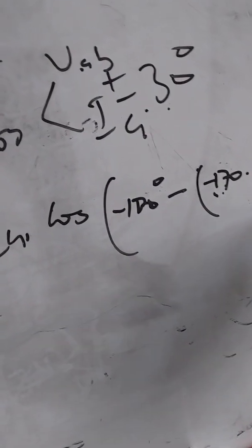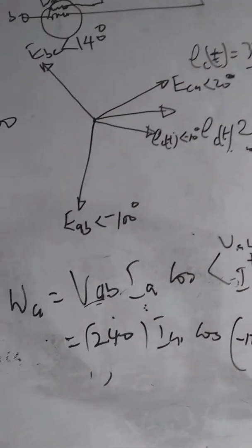You still have to subtract 30 from that again. You understand what I'm saying now? That means minus 30 degrees again, because of the positive sequence rotation that you have there. That will help you. So the same thing if you want to solve for WB.